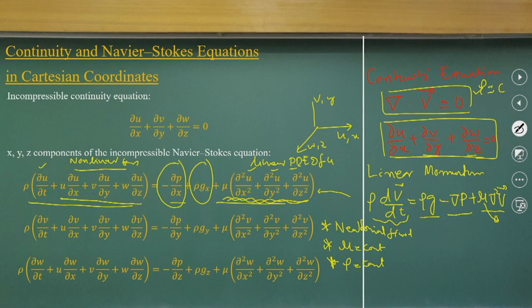For example, if I consider mu very close to 0, it may have problems. I will give you illustrations of the regions where you can see that mu is close to zero, or that the velocity does not change drastically. If the Laplacian operator of the velocity field does not change drastically, we can neglect this part. When you neglect that part, it really gives us very simplified equations.